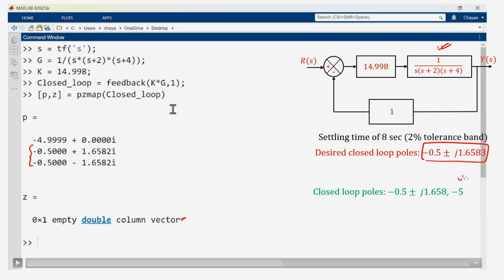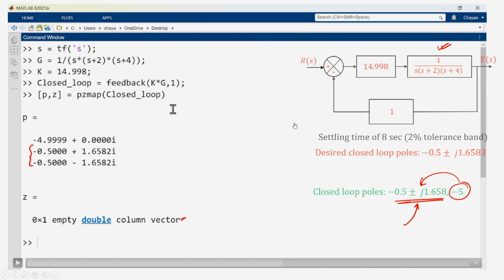Okay. So, we are expecting that the closed loop system that you have got has a third pole 10 times away from the dominant poles, which means that the output should actually mimic this second order system with these 2 poles. Okay. That is how we discussed approximation. Let us see how the step response looks like.